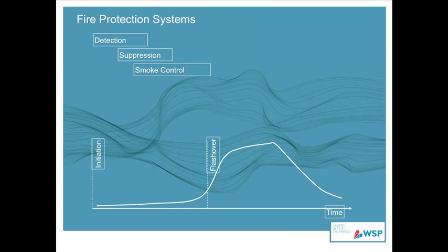In terms of life safety, the thing that kills most people in fires is smoke and toxic products. So the way we control smoke in terms of ventilation is quite important. Also protected escape routes allow people to get out of the building safely. Another strategy is compartmentation. One of the purposes of compartmentation is not only to protect escape routes so people can safely escape the building, but also to maintain the fire within the compartment of fire origin.